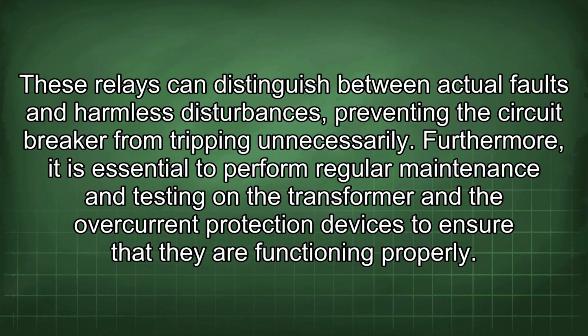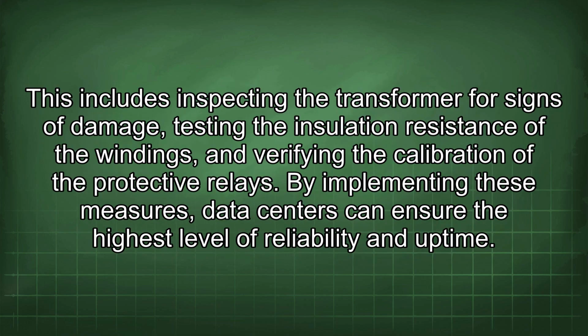Furthermore, it is essential to perform regular maintenance and testing on the transformer and the overcurrent protection devices to ensure that they are functioning properly. This includes inspecting the transformer for signs of damage, testing the insulation resistance of the windings, and verifying the calibration of the protective relays. By implementing these measures, data centers can ensure the highest level of reliability and uptime.